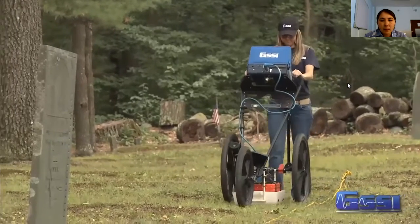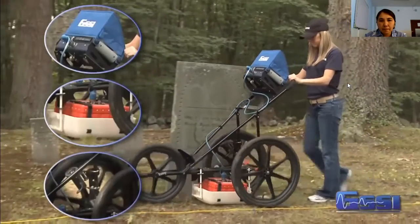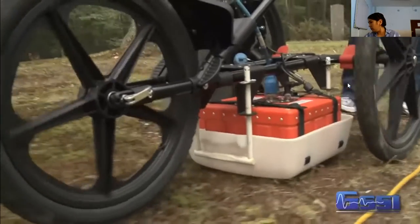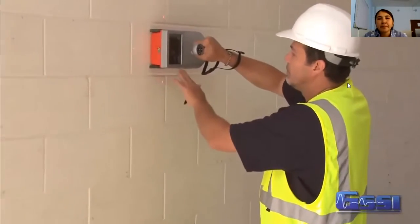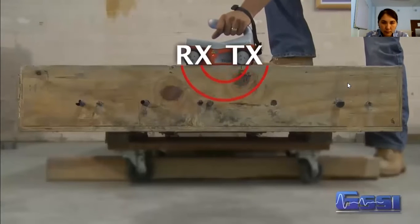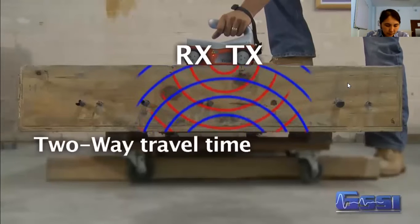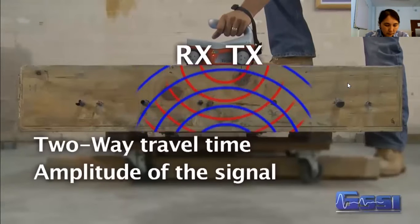GPR systems are typically comprised of 3 elements: the control unit, the antenna, and the survey encoder. Depending upon your application, your GPR system may differ from the one illustrated here. For example, the Structure Scan Mini contains all 3 components in one dedicated system. The antenna has a transmitter and a receiver. When the signals are returned to the antenna, we record a 2-way travel time and the amplitude of the signal. The amplitude is simply the strength of the signal coming back.